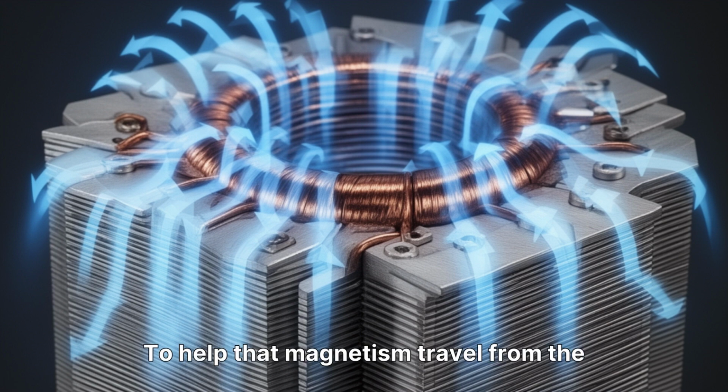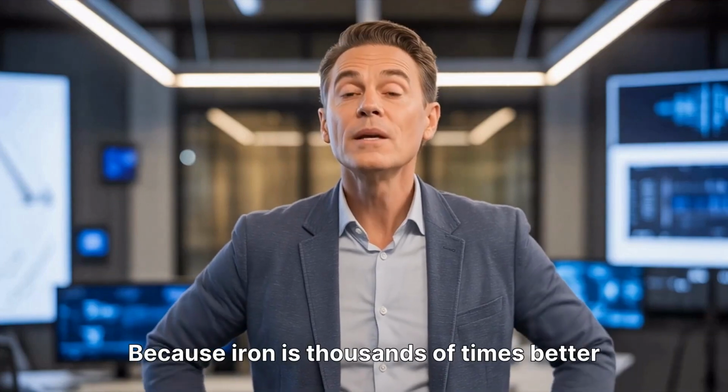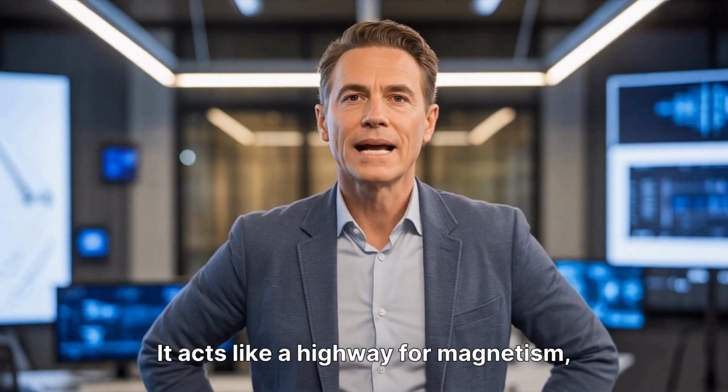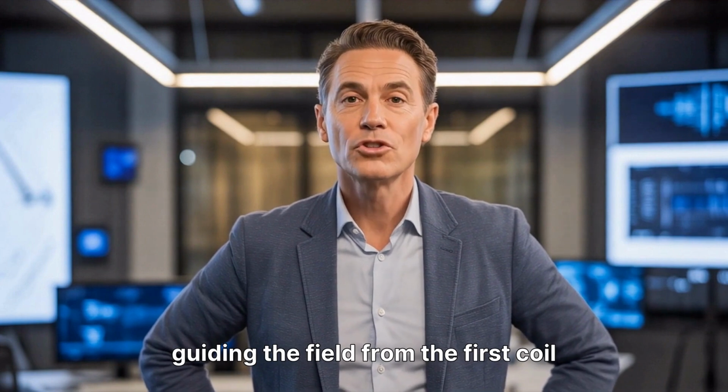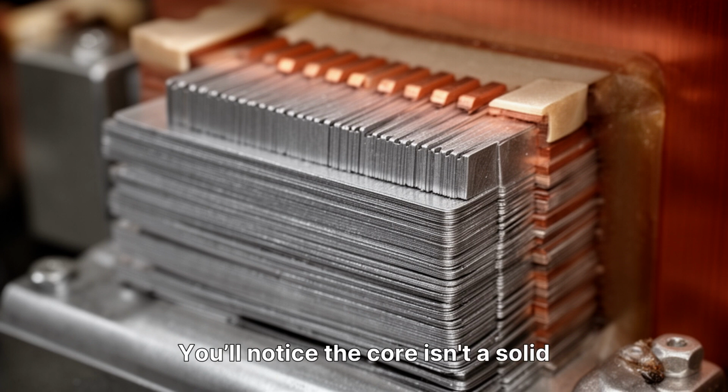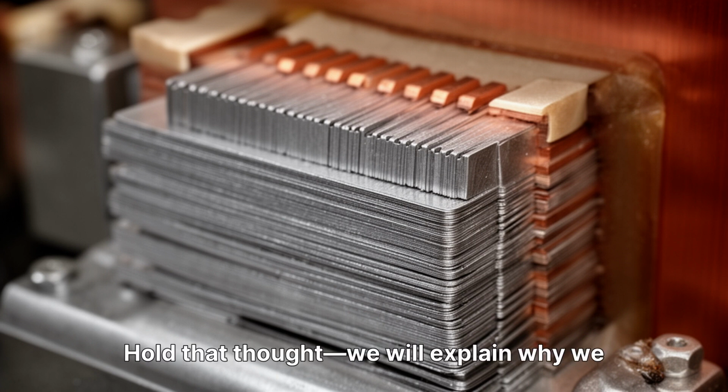To help that magnetism travel from the primary to the secondary, we place both coils on a core, usually made of soft iron or silicon steel. Why? Because iron is thousands of times better at conducting magnetic flux than air is. It acts like a highway for magnetism, guiding the field from the first coil directly into the second coil. You'll notice the core isn't a solid block of steel. It's made of thin, stacked layers called laminations. Hold that thought. We will explain why we do that in the losses section later.